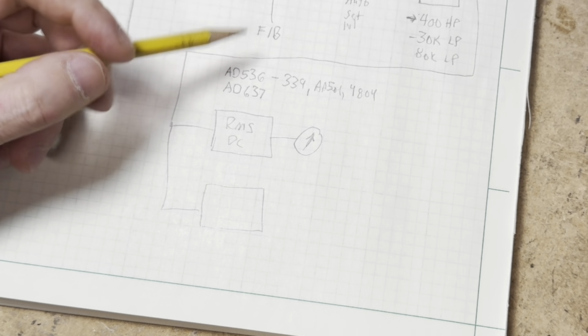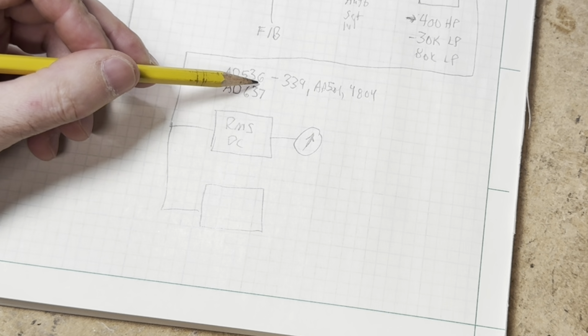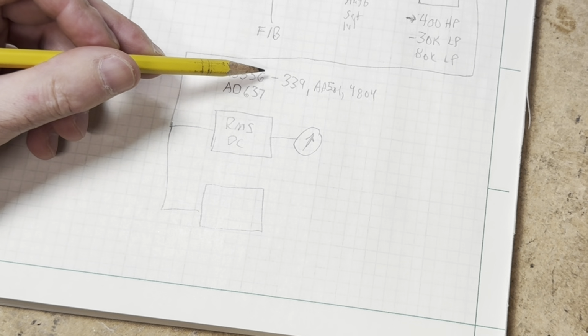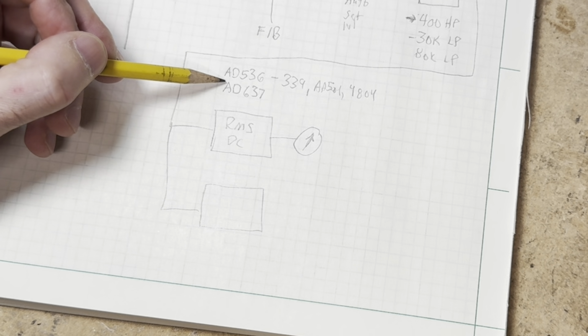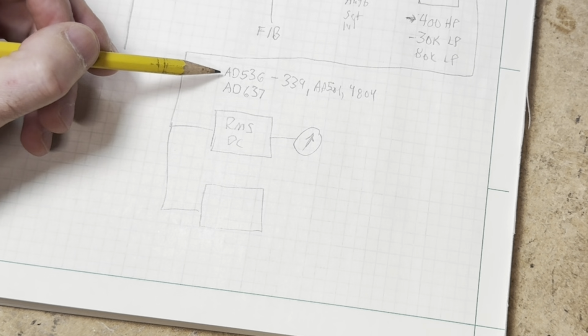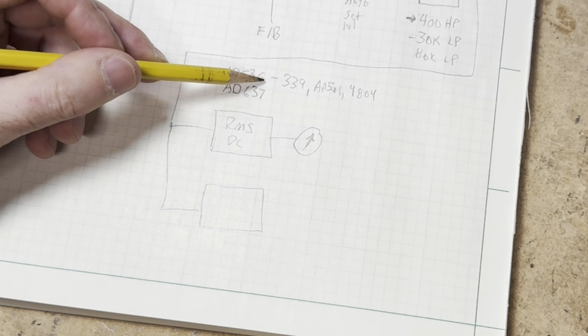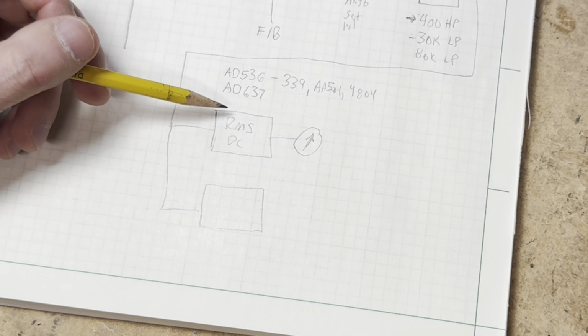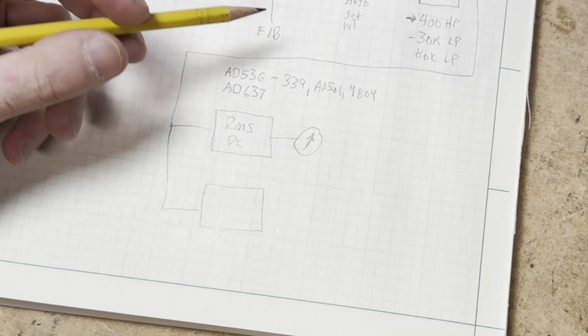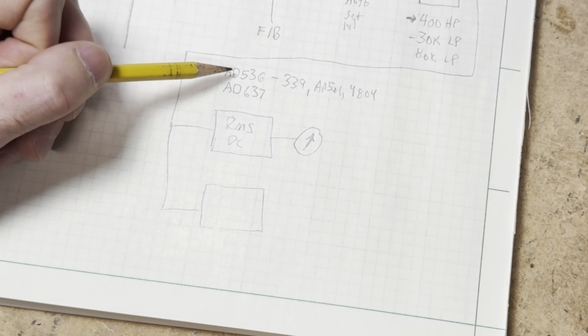Now, if you look at the 339A service manual, what you'll find is that this chip isn't listed. It's an HP branded chip, but if you look at the service manual and do a pin-to-pin comparison with the AD536, you'll find that it's the same chip. It's just been rebranded by HP, probably for proprietary or anti-cloning measures.